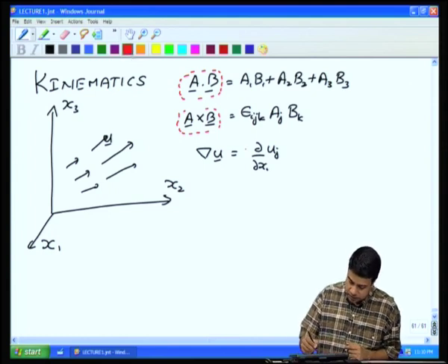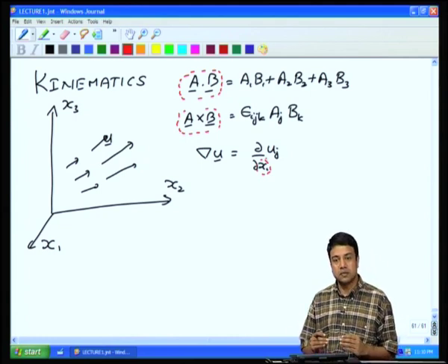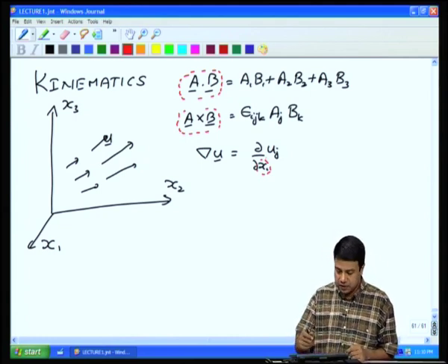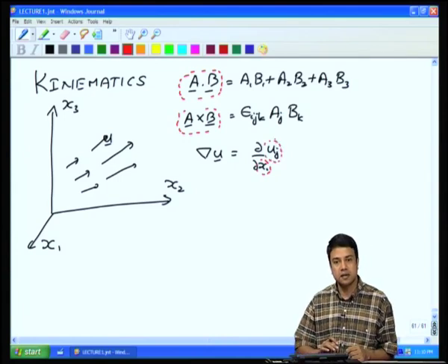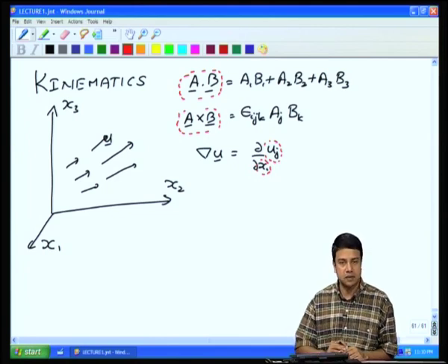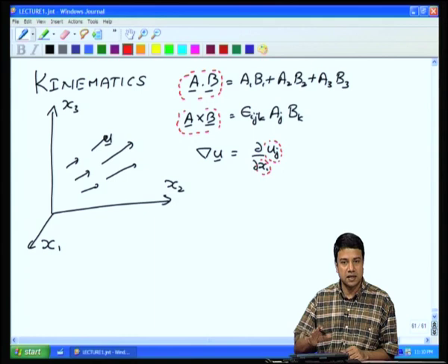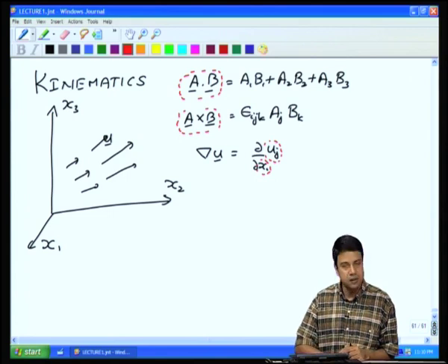There is one direction associated with the direction of the gradient, the direction in which you are measuring variations. There is a second, which is the direction of the velocity, the direction in which the fluid is moving. So, there are these 2 directions associated with it. This is a second order tensor, which has an identity once again independent of the coordinate system that you are using to analyze the problem. There were other derivatives that we had analyzed.